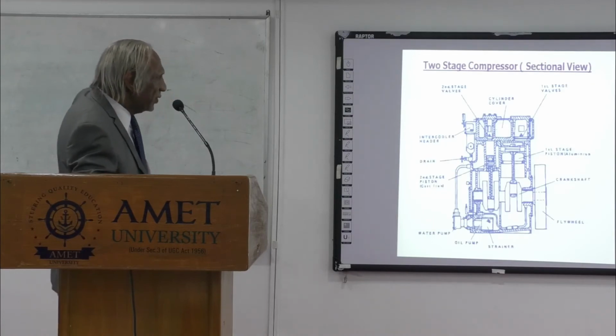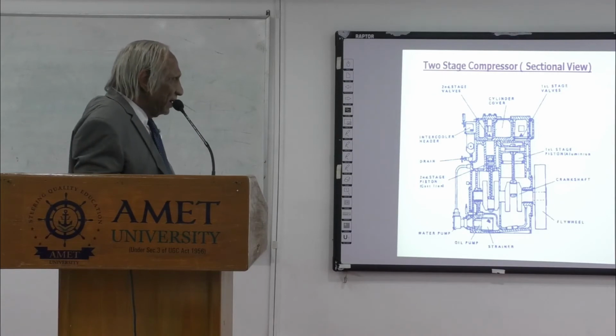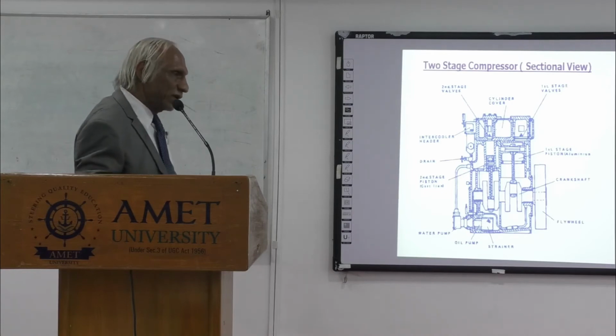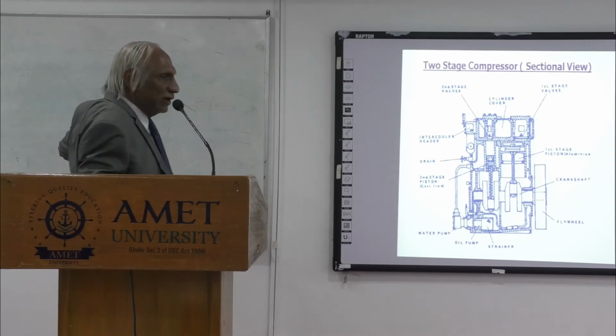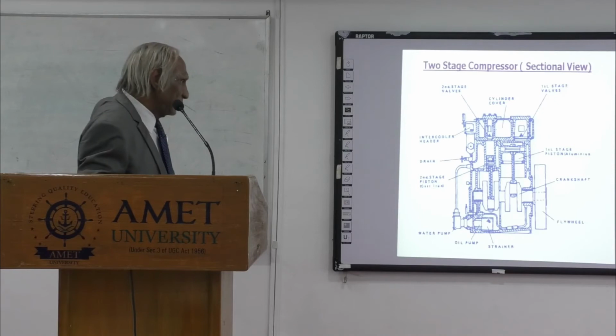Again, the components of this air compressor are similar to a diesel reciprocating engine, where you have a crankshaft with the main bearing and then the piston, and similar to the exhaust valve and suction valve, here we have the suction valve and the delivery valve. So that is the only difference between the engine and the compressor, except that the engine delivers power whereas the compressor takes in power, absorbs power.